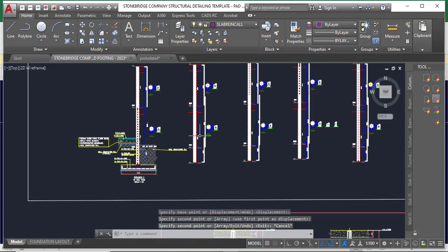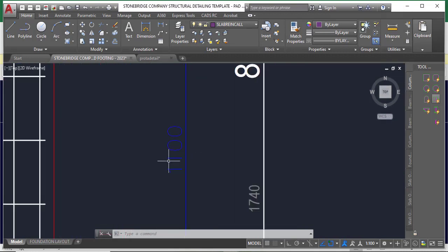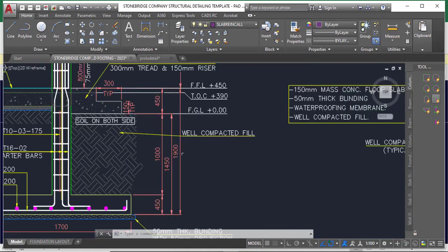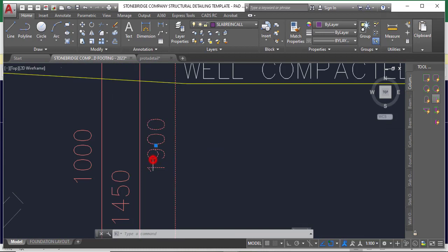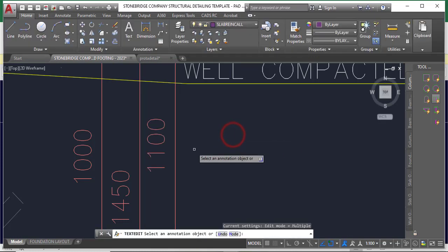So now let me look at the details of what I have in this column. You can change the height of the story. You can see for the foundation I have 1.1 meter. Over here you can change it. So here I have 1.9, right? So just change that to 1.1. So I'll be creating a replica of that with this one that I just made over here.